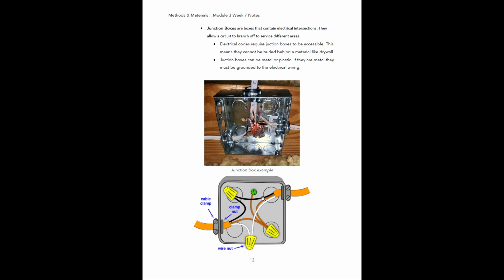If you don't do that, it can be a hazard. Like I was saying with the electrocution example, the reason that we do that with these metal boxes is because they're conductive and they have to be a part of the grounding system. So if this was done poorly, like you're seeing here, how this is usually done is there is a metal faceplate over top of this when it's not being accessed.